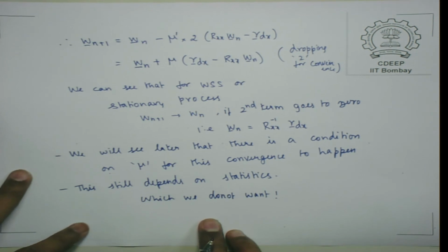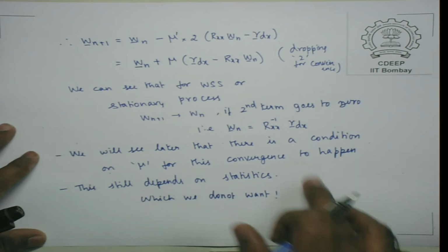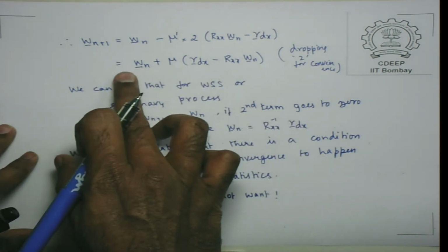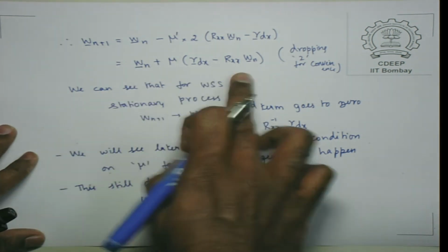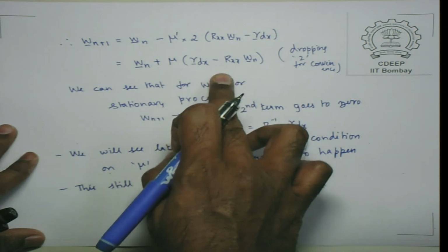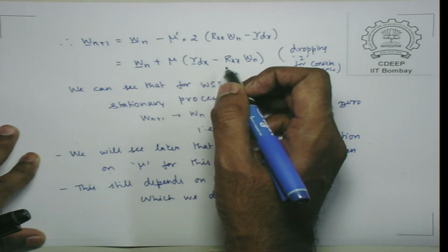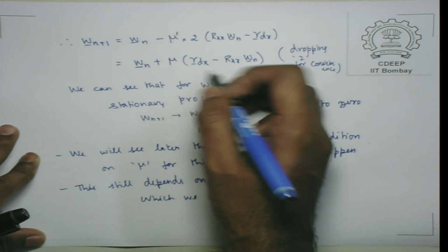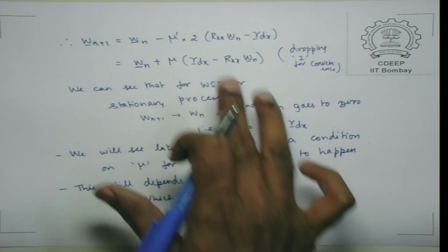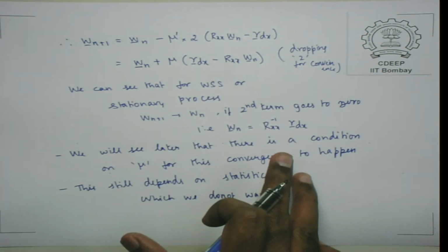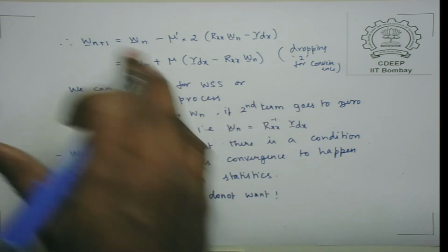Hence, we will see in the next lecture how this steepest descent like approach or stochastic gradient like approach gives us a way to update, iterate or adapt these weights, leading to an adaptive filter, but there are still some things hidden here which we would like to eliminate. Just think about this: the statistical nature of this equation comes from an expectation. We will have to see how to handle or eliminate this expectation from the equation, and if we can do that, we would have a practical way of doing this steepest descent and obtaining the optimal weight.